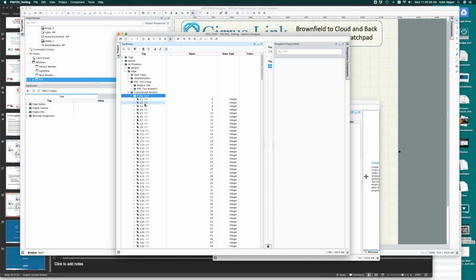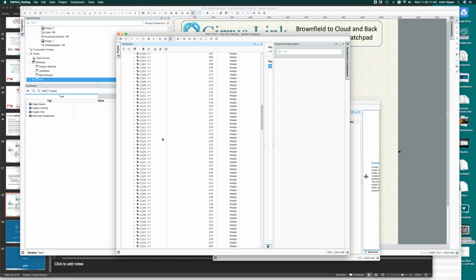So what we're doing here is on-demand polling in Modbus and picking up all of the surface cards and the pump cards required, along with some of the information. For this stroke, here's the maximum load, the number of points that we had for that stroke length, timestamp, and the well ID. Now with Ignition, we're able to build that into a folder.